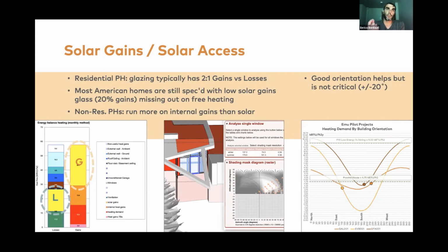While passive solar gains are important, it is possible to achieve very high quality buildings, including passive houses, or what we call PHI, low energy buildings, even if your building orientation is not due south. Especially, I'm talking about heating dominated climates.